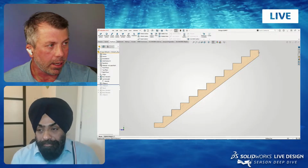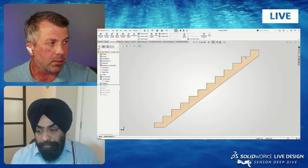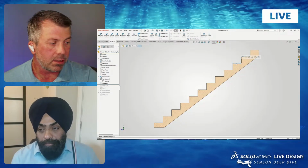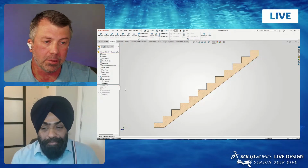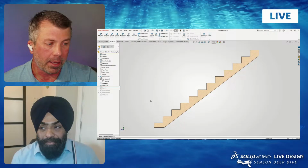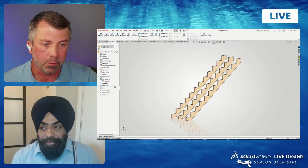Gut check: does it look right? We have all even values, 10 inches, 10 inches, 10 inches. Perfect. That's the hard part of cutting a stringer, making sure all your steps are equal. Then I pattern those out, 36-inch stringers. By code, we have to have 3.